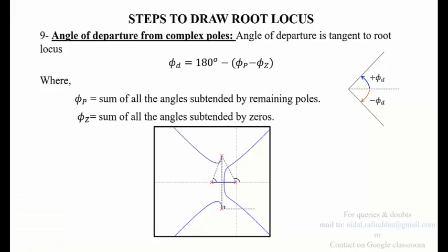So in this particular case, if we try to obtain the angle of departure, it must have come out equal to minus 90 degrees, because the pole moves at an angle of minus 90 degrees from the reference. So the pole should have started to move along this line, which is the angle of departure, and will go along the asymptote, probably from rule number 6 and 7.